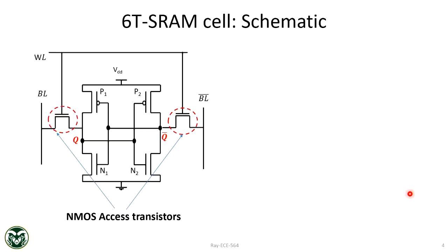Now this is the structure of a 6 transistor SRAM cell. This is a classic structure. First of all, you need to note these metal lines. This is the word line, right? It will connect the entire row of memory. So all the cells that are in a given row share the same word line. It's a metal word line. It will pass the voltage over there.